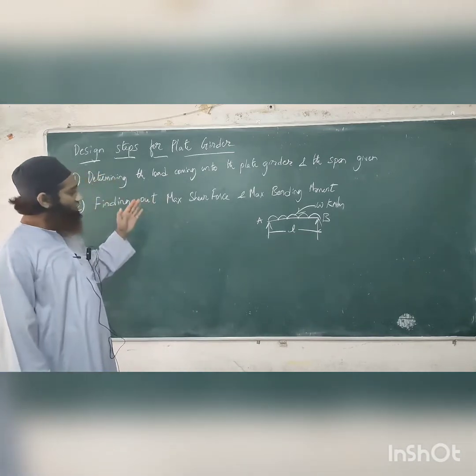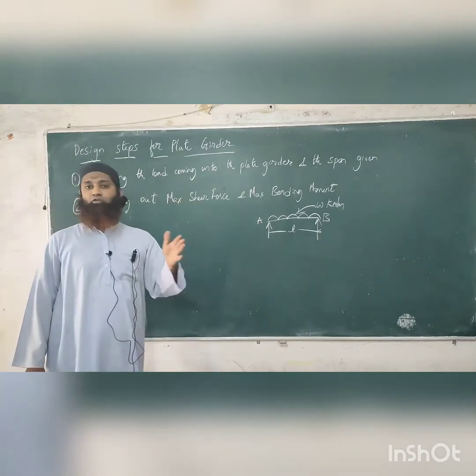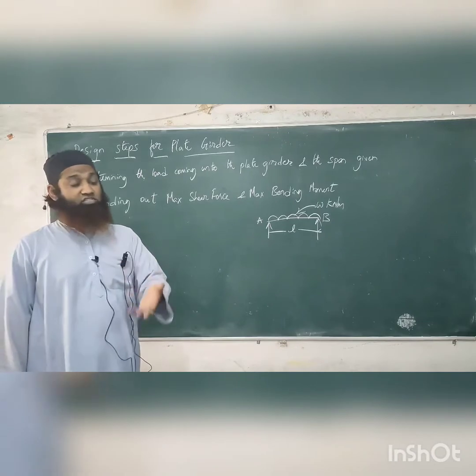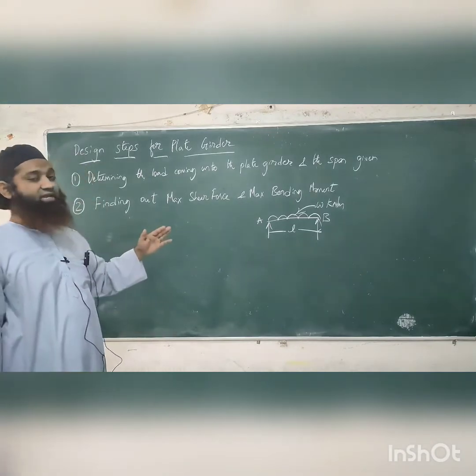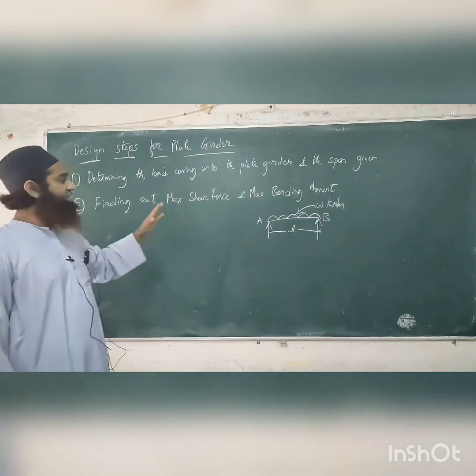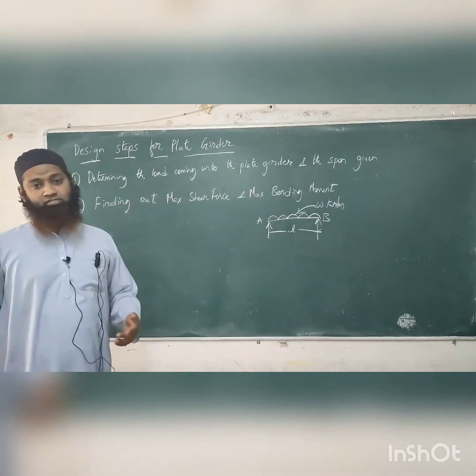So depending on what type of load is coming, we can decide what the maximum bending moment and the maximum shear force coming onto the span will be. Now this is very important because this is related to the next step, as we will be finding the depth of the girder. So the second step also, hope that is clear with you.